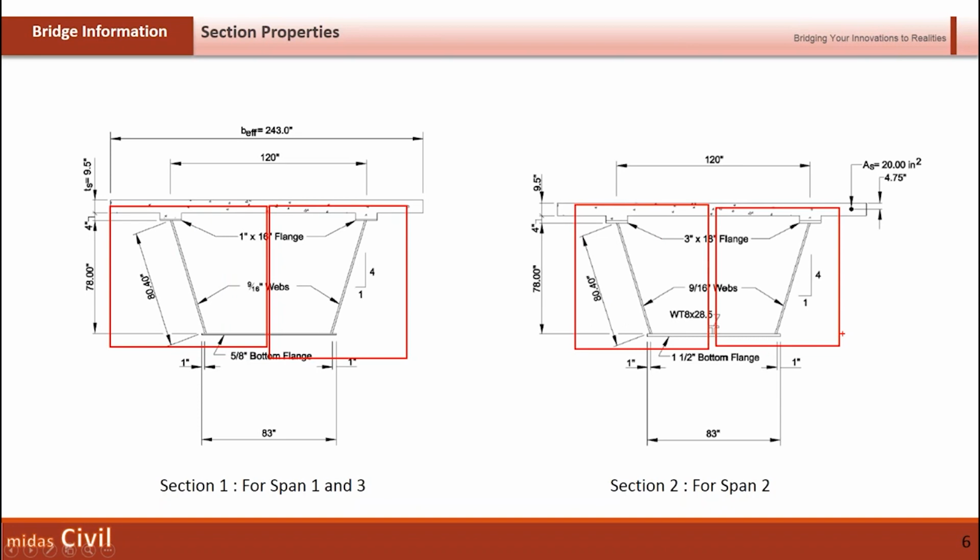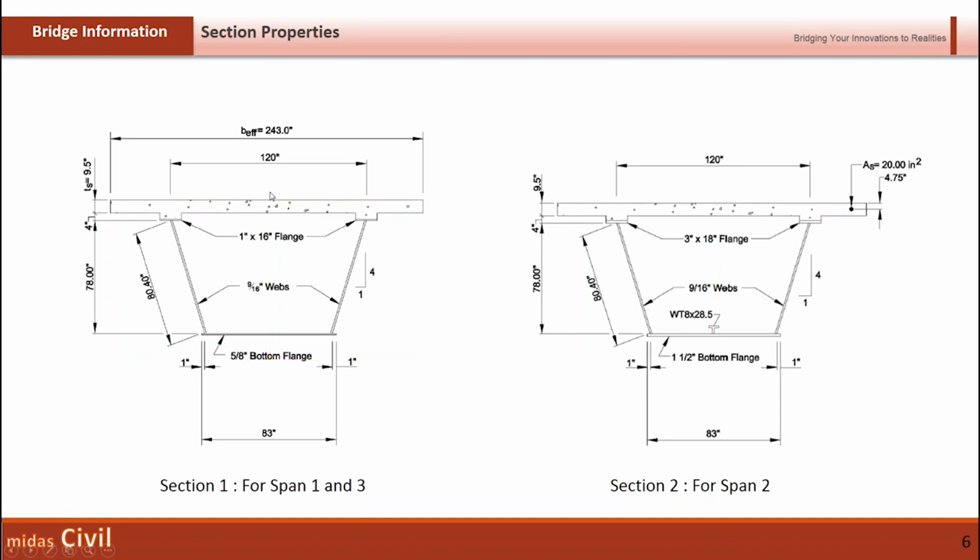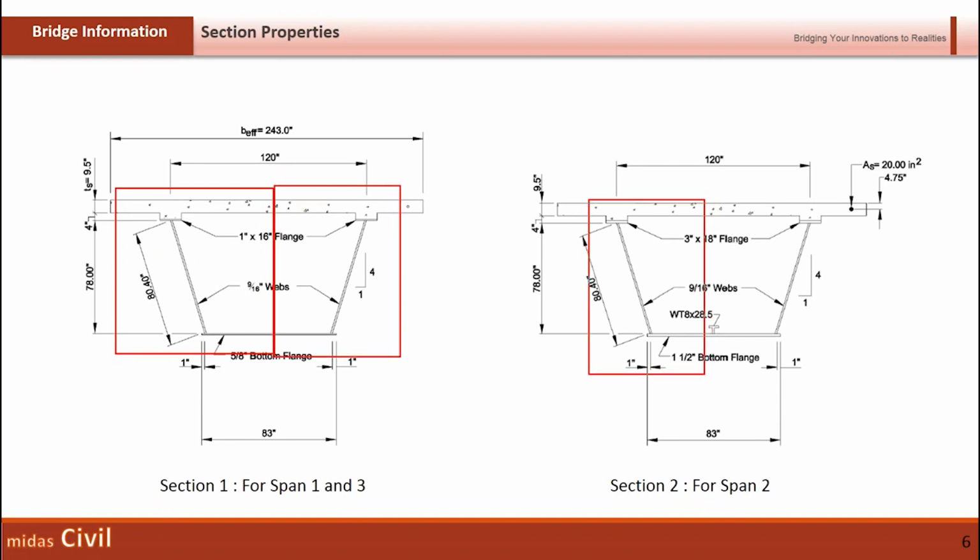If there is a torsion force, then there is an equivalent shear force that is generated inside the webs to resist that torsion. And due to this shear force, the webs might go into local buckling, so you have to consider those forces. All these design considerations are very difficult to do if you are doing it by separate I sections, right?